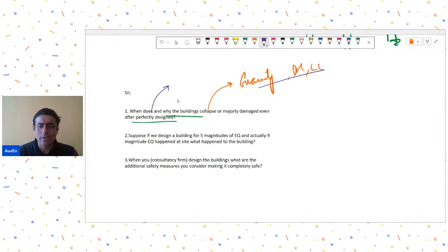If you are asking with respect to earthquake loads, then you must understand that our basic philosophy in earthquake design is that the structure will undergo damages, although we don't want them to fall down, because falling down is related to loss of life. But when we are designing for earthquake, in fact that is our design intention, that structures should undergo damages, because that is how the inelastic energy is going to be dissipated.